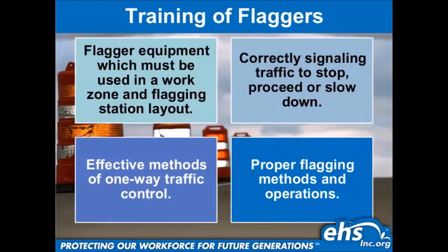But again, in my time out there working, and my time just in general doing inspections or being around the work crews, I see that sometimes they use these air horns to signal breaks as well. So let's say this danger happens when it's 5 minutes to lunch. You blow the horn, they're going to assume you're calling out lunchtime, so it's going to lose its effectiveness, right? And again, a communication device is necessary, especially when one flagger can't see the other flagger or what's going on at the opposite end of the work site.